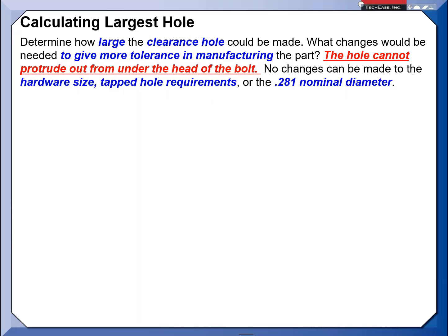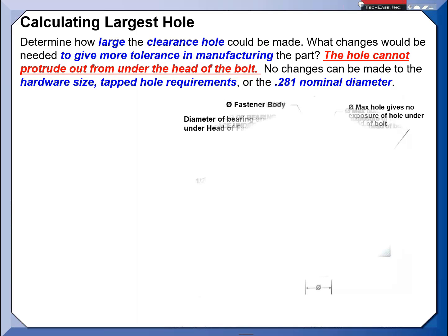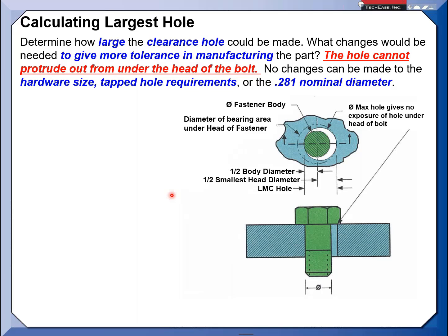So some of you may have seen this. This has been around a little bit in industry. I've implemented it at some of the companies I've been at and shown it to my engineering team. And really it's this right here: whatever size fastener you are using, think of it this way, push the bolt all the way to one side of the clearance hole.